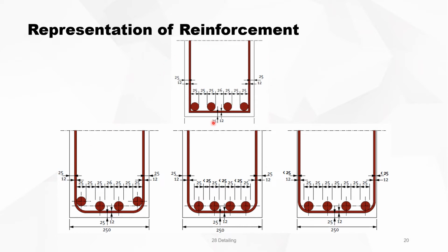Now this is a nice example of a beam with stirrups and 4 diameters, and someone made a drawing like this, and it all fits in. He must have a concrete cover of 25, and the stirrup is 12 millimeters, and the bar diameter is 25, and the clear distance between the bar diameters has to be 25. Good. I prefer 40, but this is now an example of 25. And this guy making this drawing thinks this is fine. This is now working out perfectly.